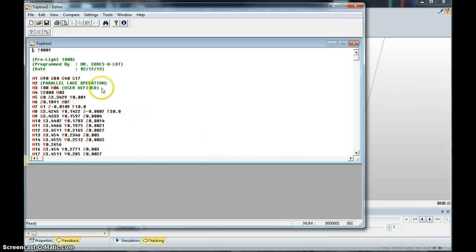And you're not done yet. We don't want to have a tool change, so let's get rid of this. Yours likely says N2, N4, N6, N8. That's fine. We're going to delete that. And what I like to put in here is a little Z 0.2. And really all that does is it makes sure that when you zero it, it's going to lift the bit up for you automatically before the spindle starts.